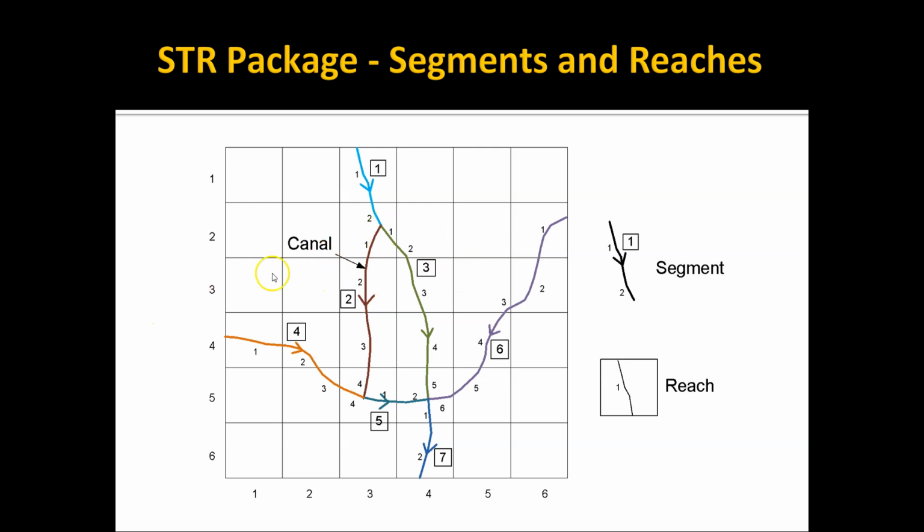Conversely, as you go from one reach to the next, you could gain water because it's a gaining reach. Suppose I'm looking at segment 3, reach 3. You take the water that came in from this reach and then add or subtract. For the sake of argument, say we add water because this is a gaining reach. That gives you a new Q down here. So for every cell, you have a Q that you can use to back calculate a stage, and that stage then controls how much water is gained or lost.